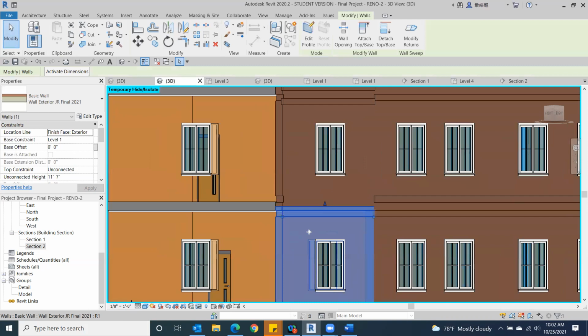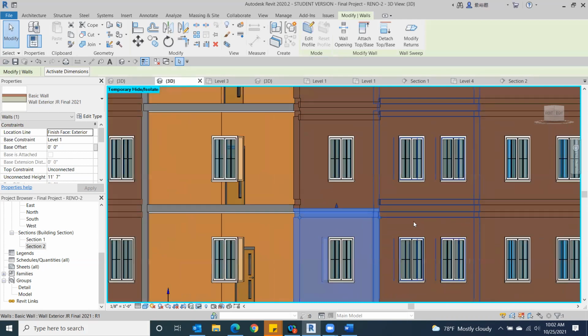So it did let me do it, but it will get a little frustrating sometimes. Depending on where you split it and what the design is, what happened there is it got rid of this sweep. So it's real important to pay attention to where these walls split. And sometimes it does get a little bit frustrating.